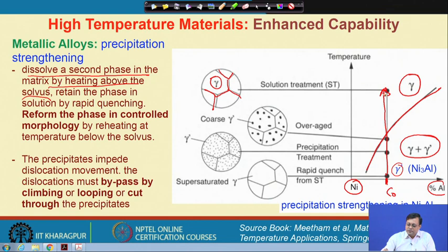After that we simply quench it to room temperature. After this rapid quenching from the solution treatment, we get a supersaturated solid solution.